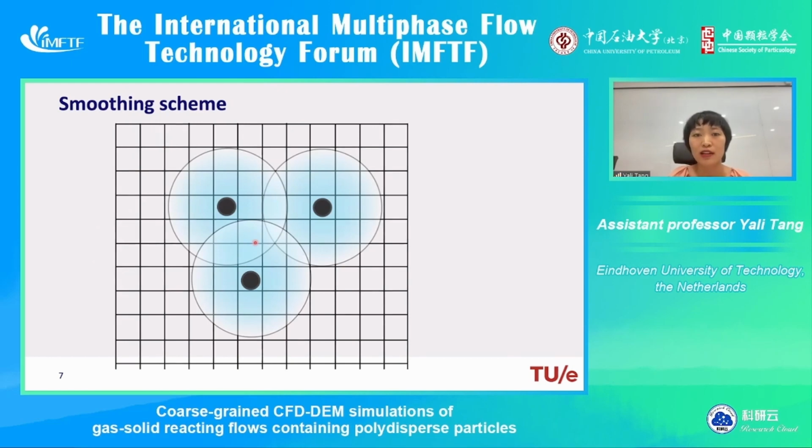This is how it visually looks. This can be done simply by solving a diffusion equation of the transferred property phi. This phi is a general quantity, which can be, for instance, the solid volume fraction, or a coefficient like the heat transfer coefficient, etc. And here the diffusivity is the only thing we need.